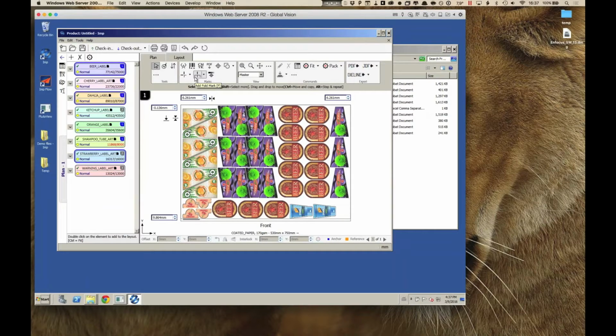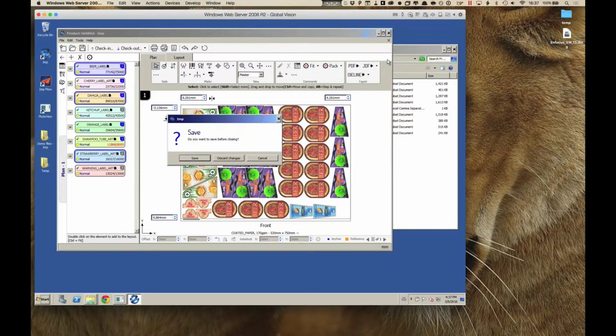Okay, so this was simple. This is very similar to what we did 2 weeks ago for rectangular products. And in fact, if you have rectangular labels and irregularly shaped labels, or something else than the label, then you can also plan them on the same layout. So just add all of them as unbound components, ask Imp to plan that, and it will extract the die line from those jobs that have a die line. If there is no die line in a job, it will automatically use the trim box and do the imposition that way. So it's very, very flexible in that sense.